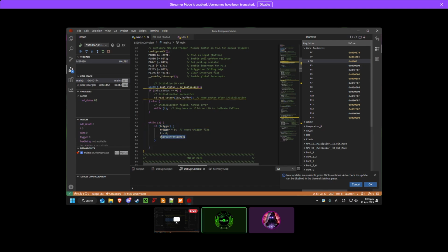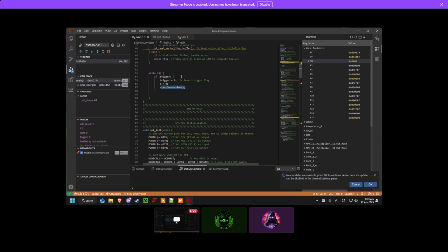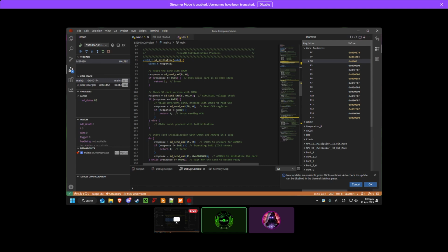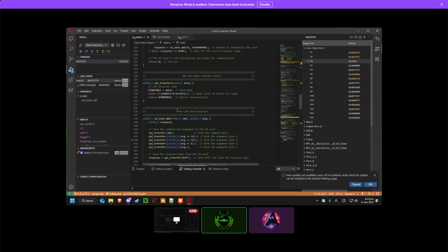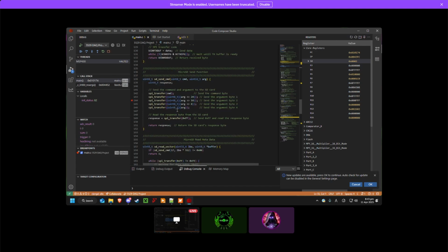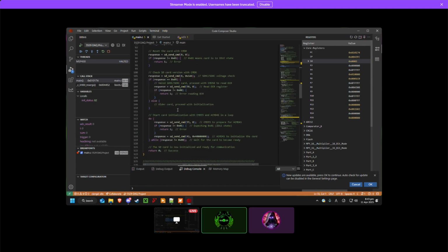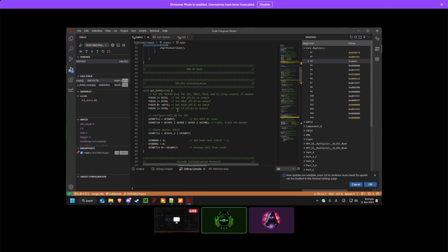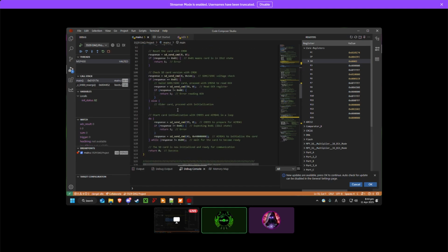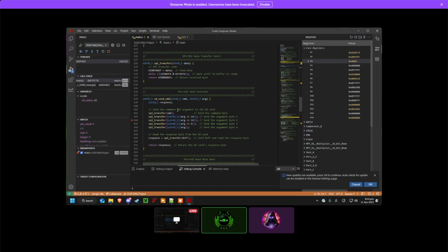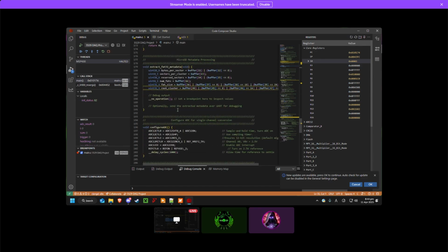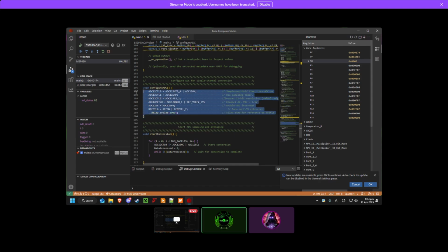When we set the trigger to 1, we start a function called start conversion and reset the trigger. So start conversion function has a prerequisite. We actually need to configure the ADC. That was done in a separate function. Here, this is where we actually configure the ADC.